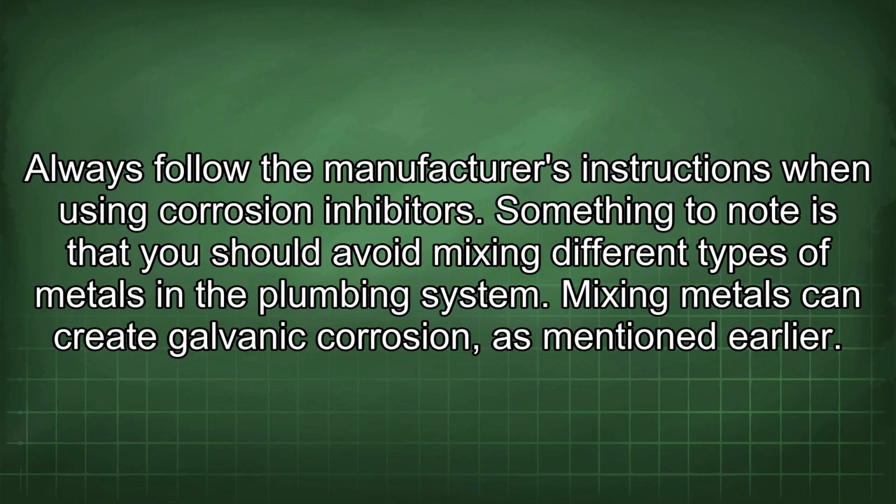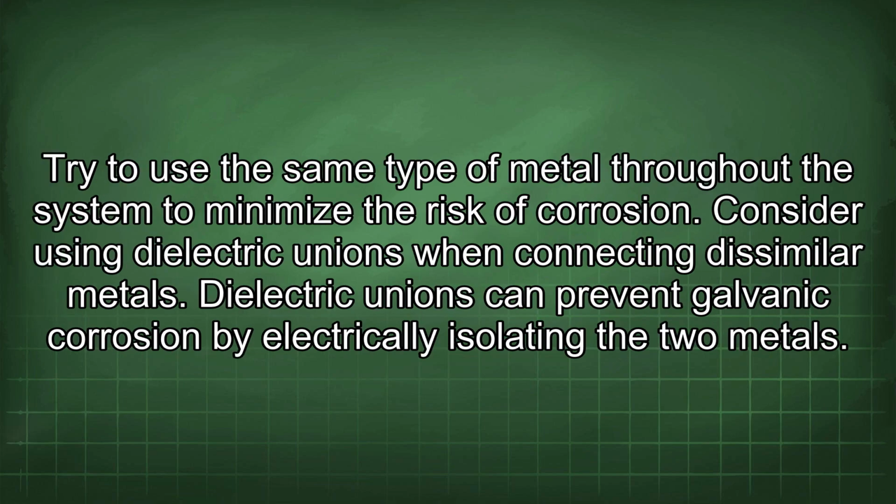Something to note is that you should avoid mixing different types of metals in the plumbing system. Mixing metals can create galvanic corrosion, as mentioned earlier. Try to use the same type of metal throughout the system to minimize the risk of corrosion.